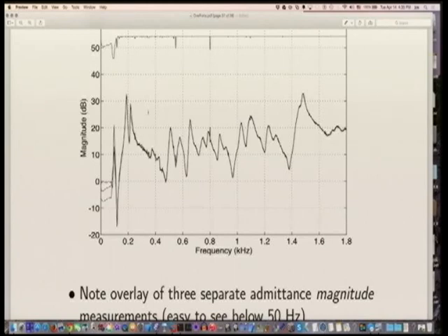It's also called a scatter plot. You're just looking at raw data. You haven't averaged anything. And everything should line up on top. No matter how you excite the system and no matter how you measure the output at the same driving point, you should have the same frequency response, the same transfer function. So they should all overlay perfectly, right? Well, they won't. I guarantee you. I don't care what you're doing.